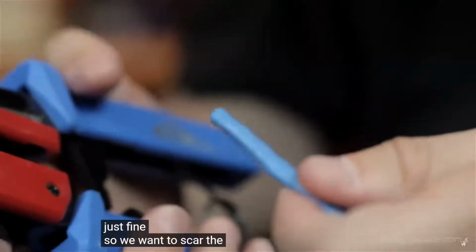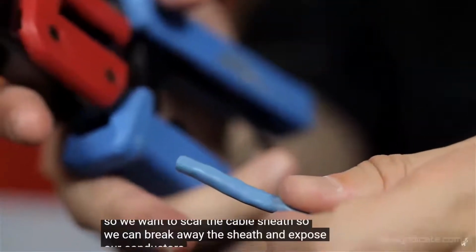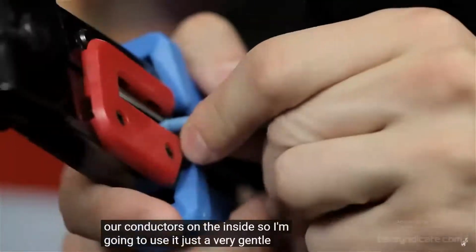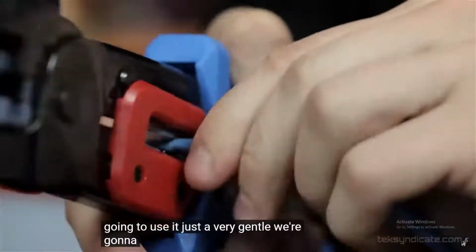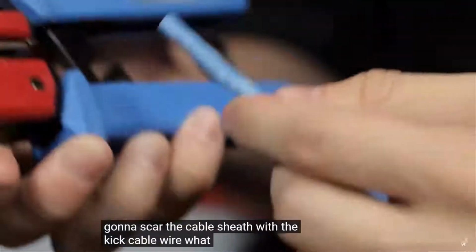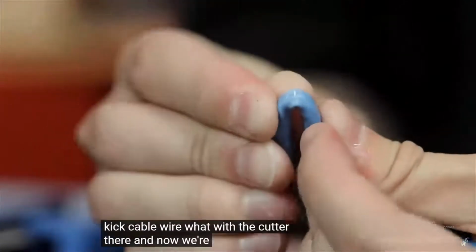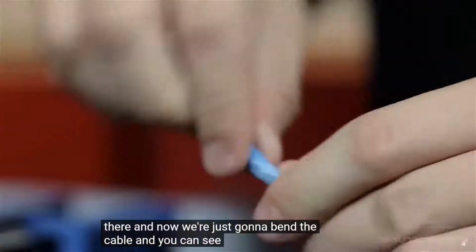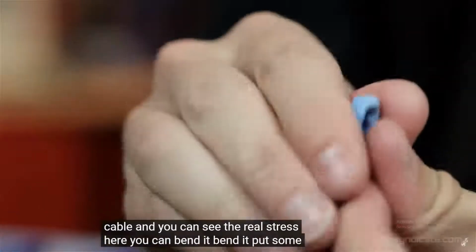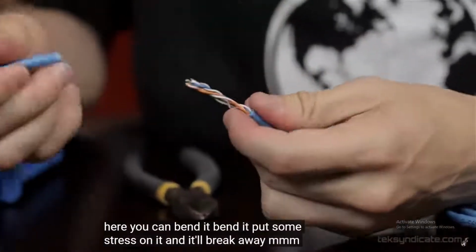So we want to scar the cable sheath so we can break away the sheath and expose our conductors on the inside. We're going to use it very gently. We're going to scar the cable sheath with the cutter there. And now we're just going to bend the cable, and you can see the real stress here. You can bend it, and you can put some stress on it, and it'll break away. All right. Get the sheath exposed.